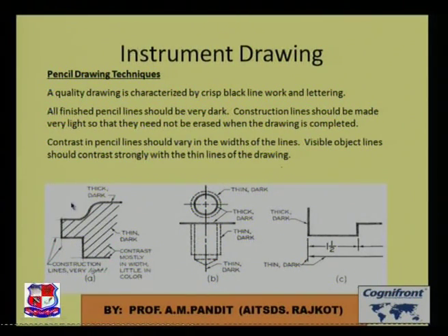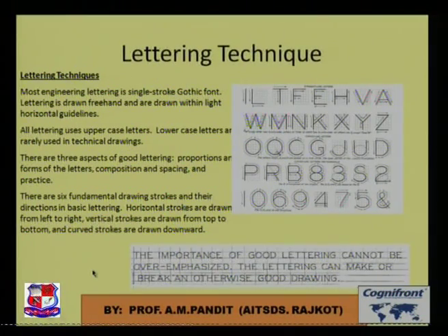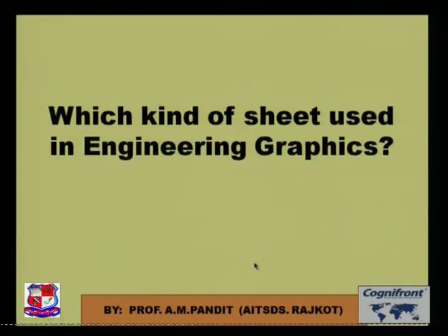If we have taken some sort of projection, we should not erase it. It should be thin, but our object would be thick and dark. Lettering. Ideal lettering should be like this. The letters should be equal in length and equal in width. Nowadays, stencils are available in the market. Using those stencils, we can draw proper lettering in our drawing.